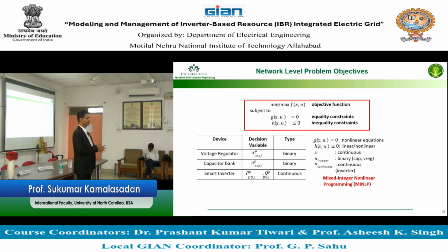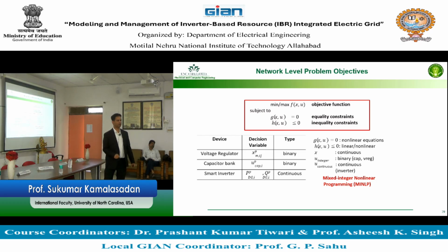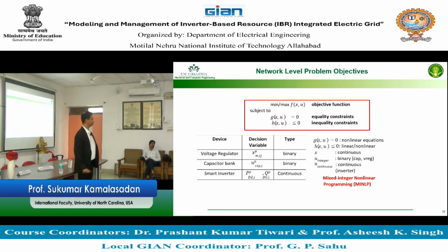Unfortunately, in an electric grid power problem, when you write a power equation, it is non-linear. Why is it non-linear? Because you have voltage squared divided by R, a fundamental thing as far as power is concerned. For current and voltage it is not a problem. So this can only be solved through non-linear solvers. Such solvers are called NLP solvers, or non-linear programming solvers.